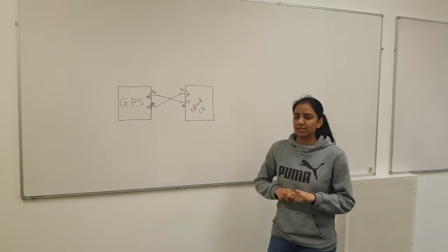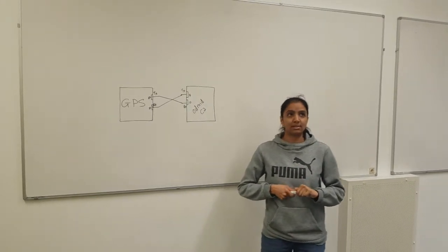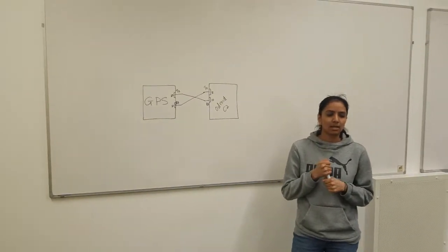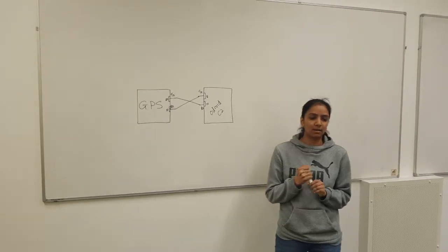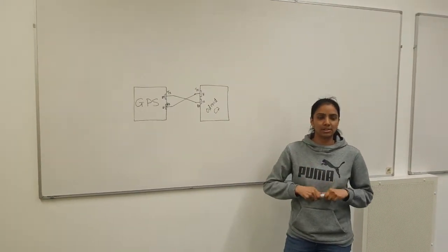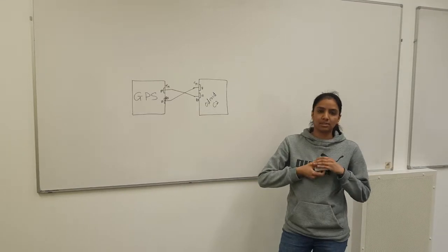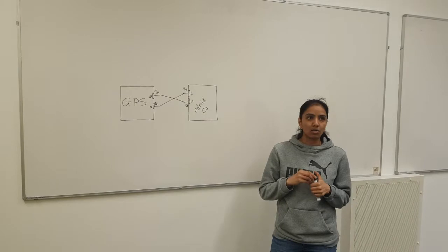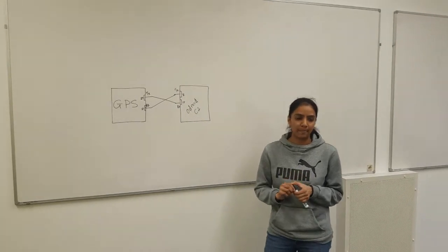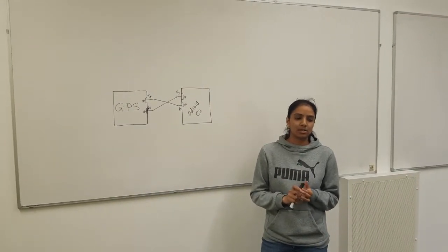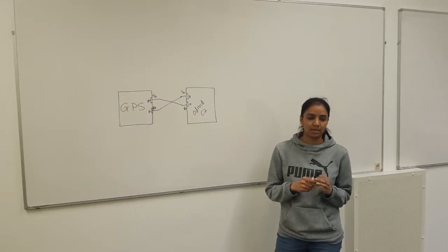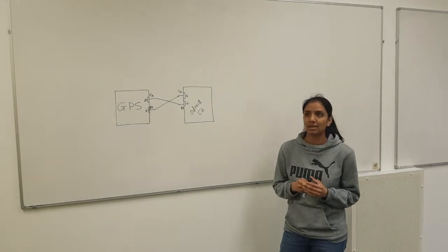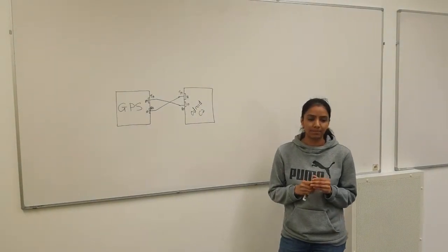it is using u-blox 6 protocols to communicate, which displays the longitude and latitude of the position of where the GPS is. It also uses the NMEA communication protocol, which uses the GGA representation of the GPS, and that is on the GPS by default. It updates at the rate of 1 Hz by default, and the serial communication baud rate for the GPS is 9600 by default as well.